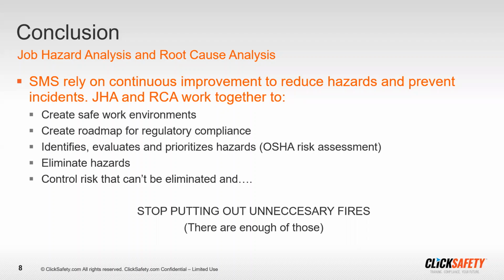Administrative controls, creating methods so that individual is not exposed to the hazard in their work routine. So you can't engineer out the hazard. That individual still needs to approach a working edge, but how can you put in controls so that there are processes and procedures that that individual has been trained on to lessen the severity and the risk of falling in this example. So engineering controls, administrative controls, finally the use of personal protective equipment.